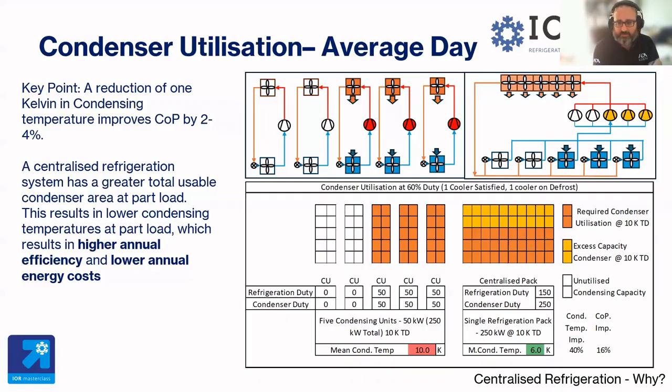As we know that our COP has improved, so our THR will actually have reduced somewhat, which gives us a further marginal gain in efficiency. Our condenser temperature doesn't have to be that high. We also get maybe a third order consideration. Because we have more surface area, we have a reduced THR, we need less airflow across the condenser. So the average fan speeds will reduce.